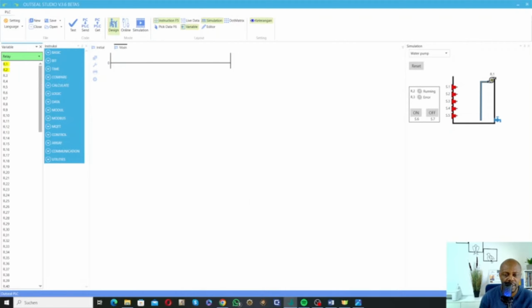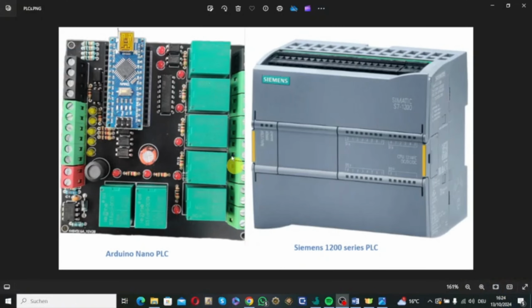If you look here, this is an Arduino Nano. It's connected to this board. This board has some relays. Your Arduinos work with 3.3 volts and 5 volts, so under 5 volts generally, but sometimes your output devices can work with 12 volts, 24 volts, 240 volts, and what have you. And you don't want to connect them directly to your board. If not, you're going to destroy the board. You're going to fry it. And so you have your inputs and your outputs.